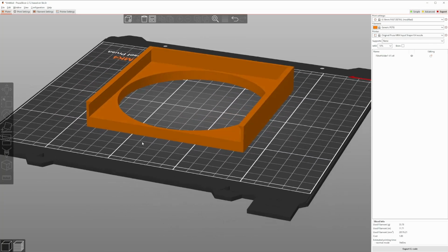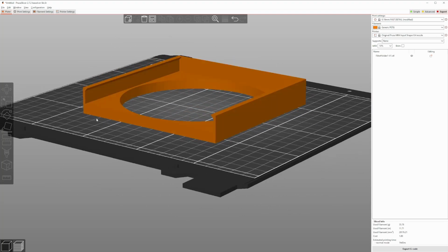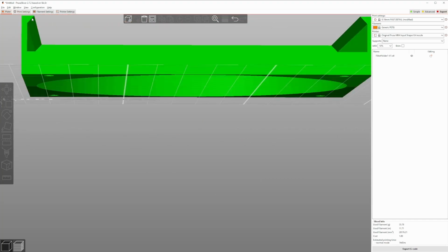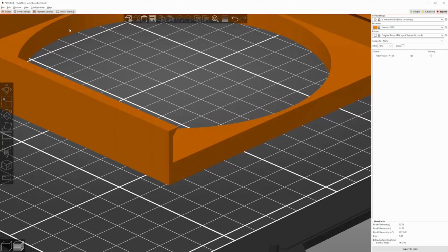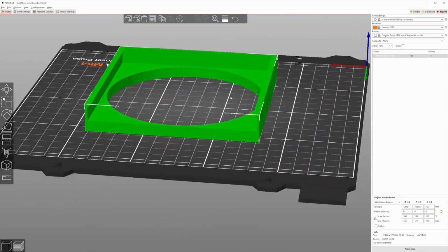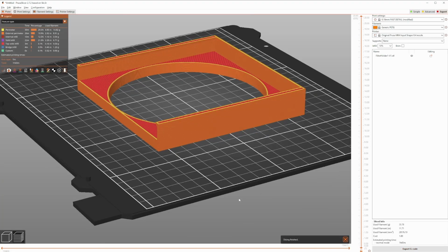And so I've imported my 3D model, and this is how I want to print it. And I designed it this way so it's easy to print. It doesn't require any supports because these overhangs right there are not, like, my printer can handle that, and most printers can because it's just 45 degrees. And so this one's easy to print and it doesn't take much time. And so I can slice this and we can see it takes an hour and 40 minutes.